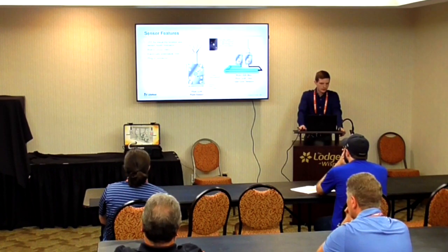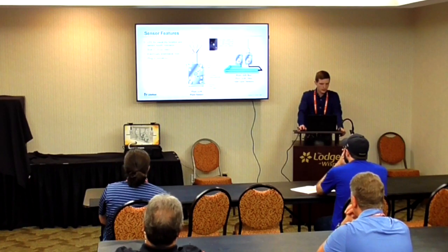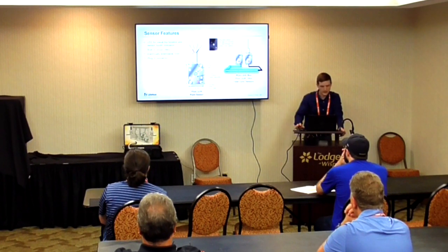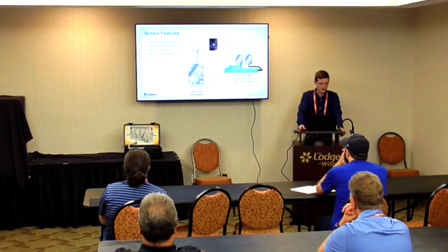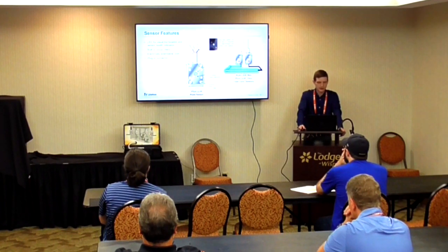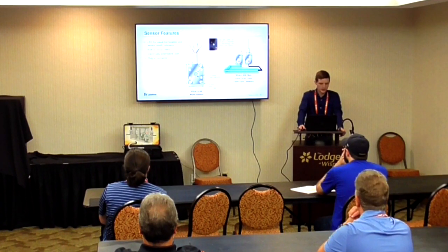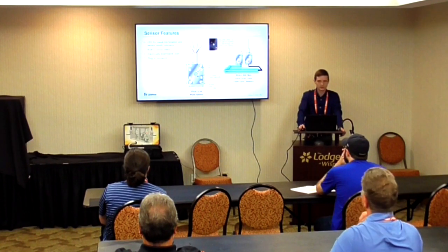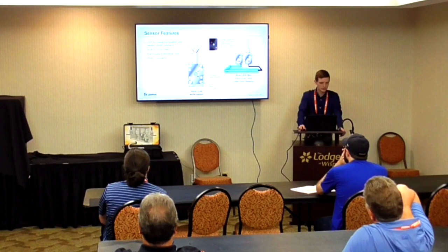Some of the features that you'll see oftentimes used with these light sensors is the light that you'll see flashing, which tells you that the sensor is still good, it's in good health. There is a built-in circuit check, so you'll see that there's 4 wires here. One of these is going to go back to the relay and tell it that it is okay, that this sensor has not been damaged, or the line going between the sensor and the relay itself has not been damaged.